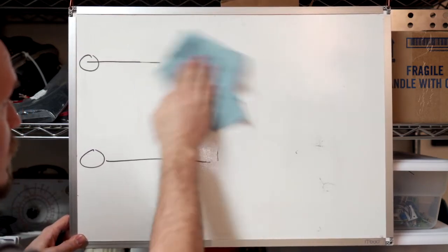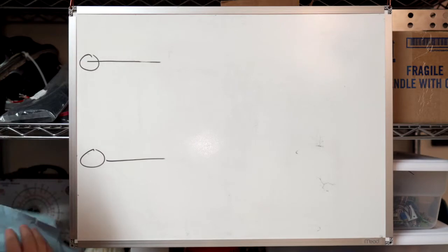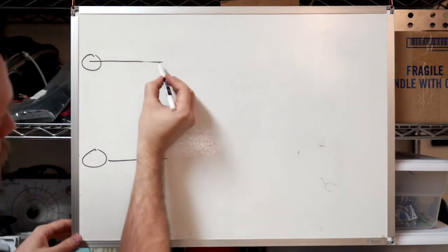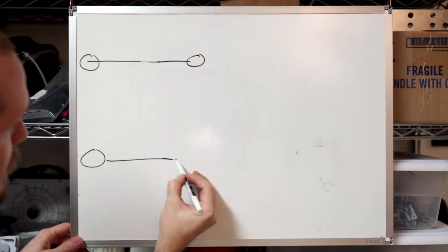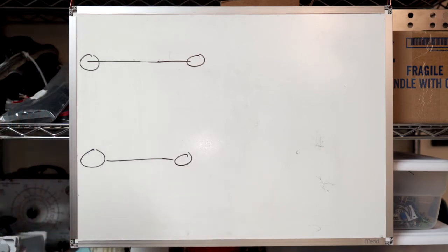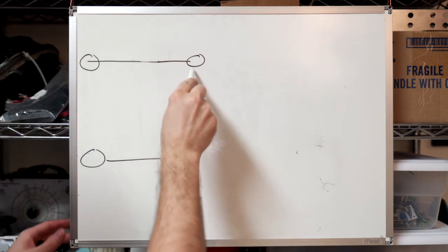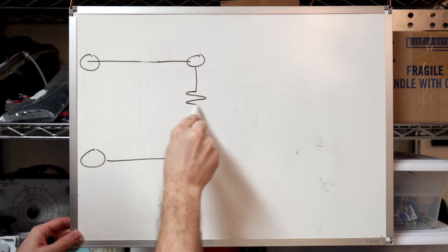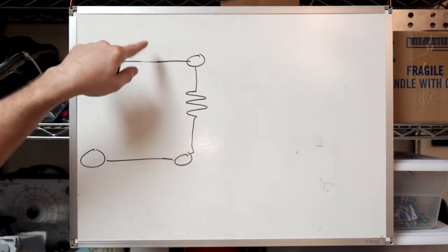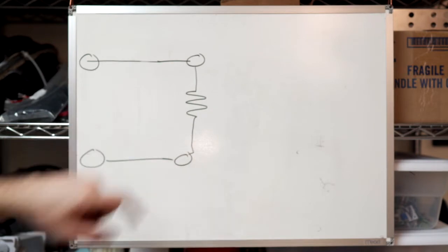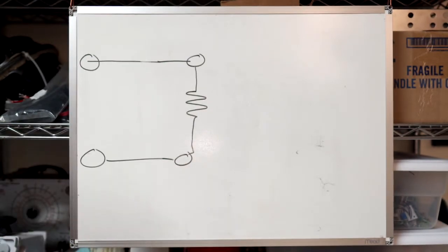So imagine, for instance, we're measuring a solid-state amplifier, and we want to find the output impedance of the solid-state amplifier. If you just started dropping resistances in here to find out the point at which this value is halved right here to find out the output impedance, because solid-state amplifiers, generally speaking, incorporate a lot of loop negative feedback, they'll adjust the output voltage in accordance with their loop negative feedback to compensate for current draw.